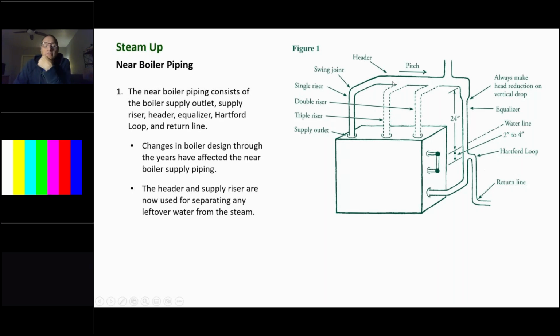So it is vital that you follow the manufacturer's instruction on the pipe sizes required for your risers and your headers. Because without that, we will be sending wet steam out to the mains, so it'll be pulling water as its steam condenses in that main. If it's not big enough, it'll take water out with it every time it fires. And then that can cause low water conditions and other problems throughout the boiler. So that's why we want to produce that clean, dry steam.